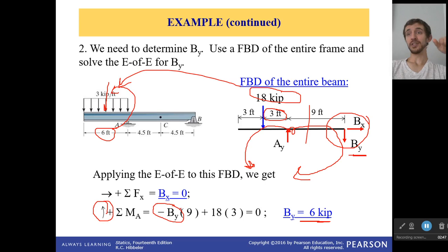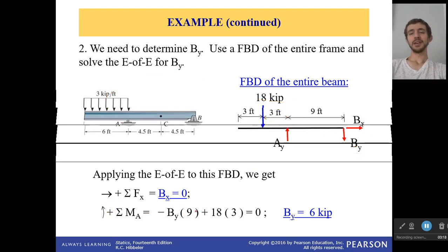Do not look at the forces to determine, well, it's going down in the negative direction, so it's negative. That will mess you up. Just keep both of them positive, even if it's looking negative, and then determine, okay, is this going to be turning it clockwise or counterclockwise? Considering how that was recorded, it might have looked like the opposite, but you know what I mean. You have to think about the way it's turning it, not just the direction of the force itself, or the direction of the position vector itself. So please remember that.